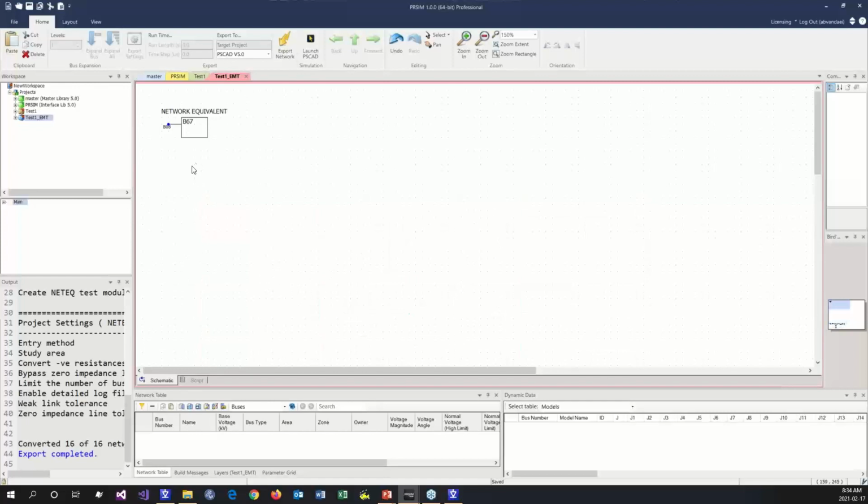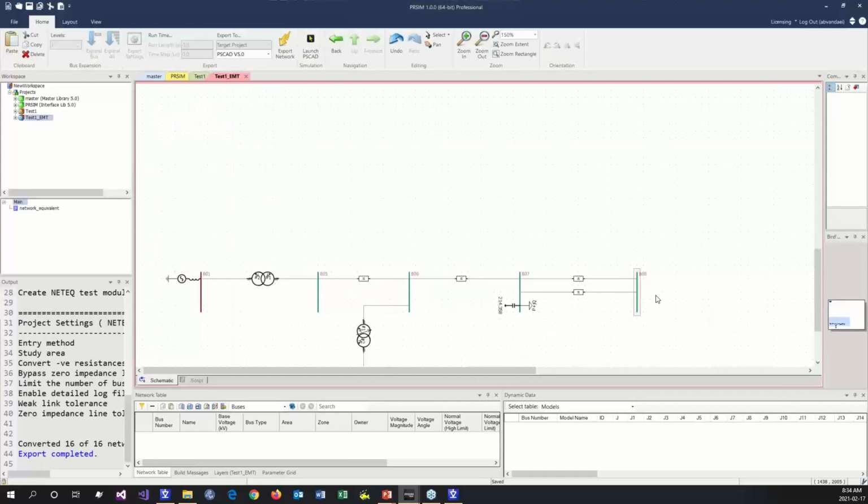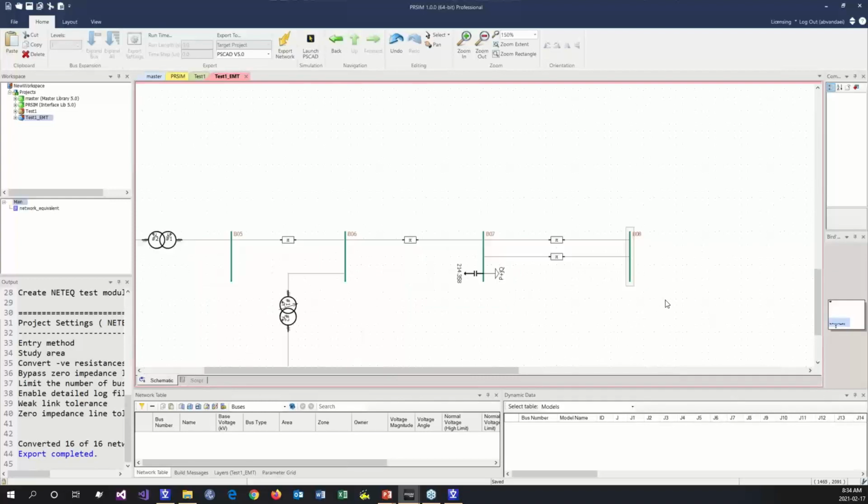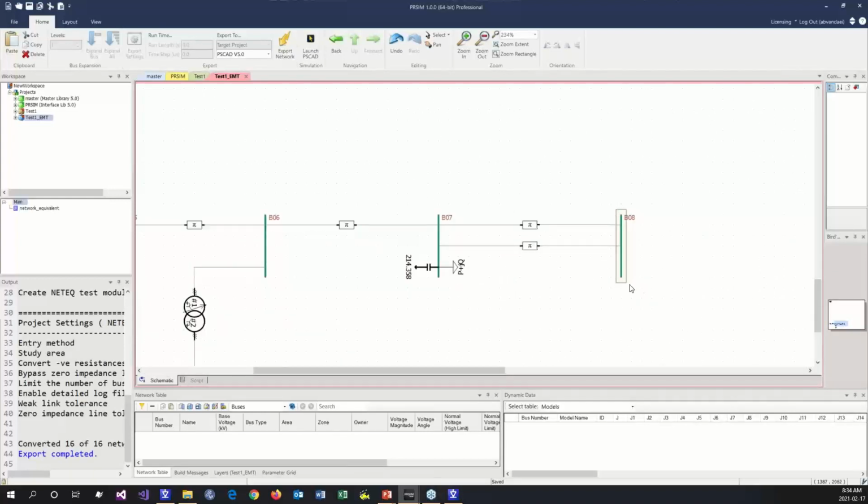And for example, if I dive into this module, this is going to be a simple AC source. The other two types of components which normally appear under this module are the transformers as well as RLC branches. And with the combination of those three, we model the rest of the system, whatever it is, for each specific case. Another cool feature is that we add a sticky note to all those boundary buses to make it easier for you to differentiate them from the normal bus bars in the system.